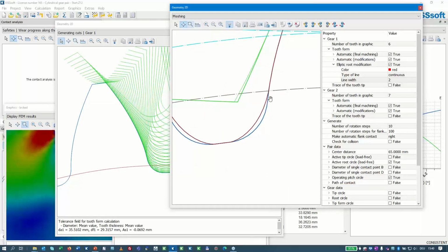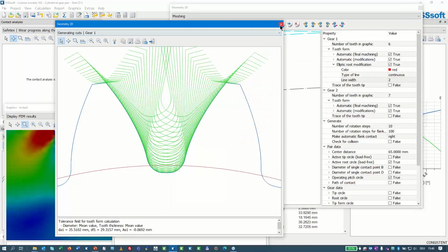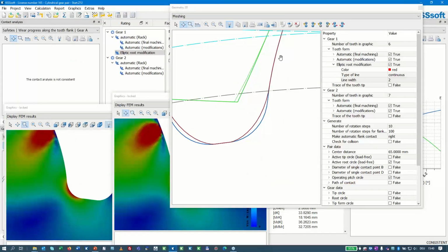This is what then gives here the blue shape. However, for plastic gears, I can use, say, wire erosion to create a cavity. I'm not bound to this generating process, and I can do this elliptical shape shown here in red.